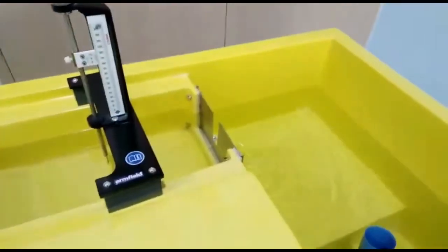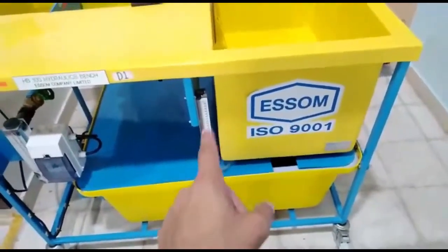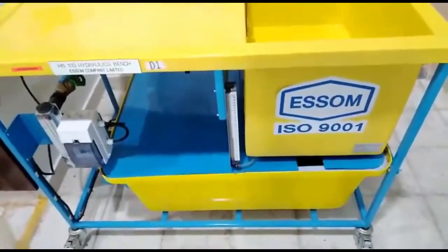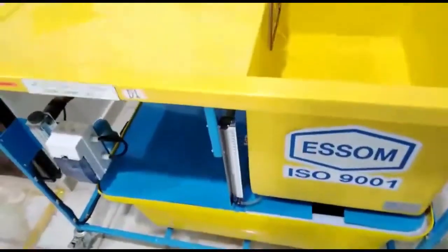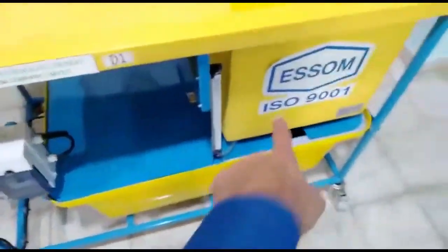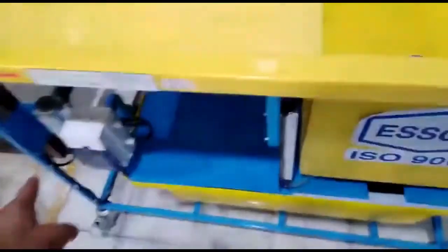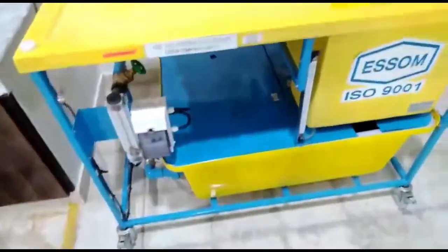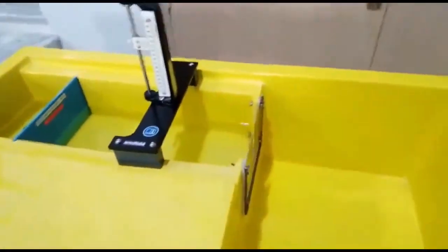So I can note this value, 110 millimeters. Also remember that you can measure the flow rate from this gauge, which is volume divided by time, volume collected in a particular time, right? So you can also find the discharge from that relationship, but these two should be nearly the same, right? So I'm taking that value of 30 liters per minute. So let me show you the calculations afterward.